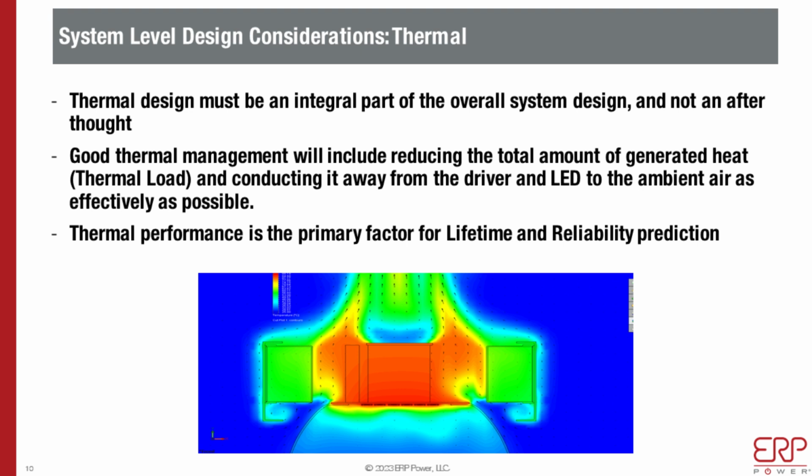So the second sentence pretty much defines what a good thermal management should be. That should include reducing the total amount of generated heat, essentially called thermal load, and effectively conducting it away from the heat generation sources, which are the driver and the LED, which in this case, the LED are POC modules, combining them both. And you want to conduct it to the ambient air as effectively as possible.